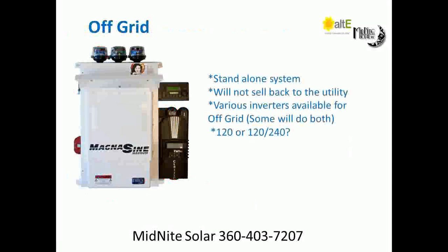Some off-grid systems get pretty big battery banks, and when they do, you need a big enough battery charger to actually fill them. So sometimes I've actually seen extra inverters put in more for the battery charger than to carry the load. But for the most part, to size an off-grid system, the first thing you need to know is what's the biggest instantaneous load I want to run. That will give you the wattage of the inverter. And then you need to know, what is my consumption over a 24-hour period. And with that information, you can calculate out how many solar panels you need, how many batteries you need, how many charge controllers you need, what inverter you need.